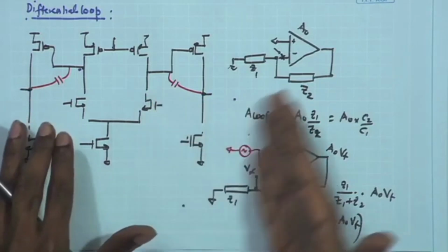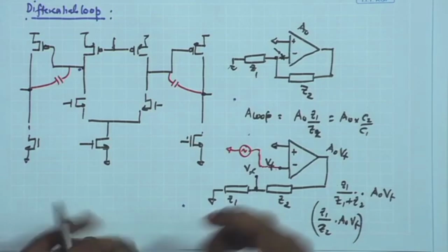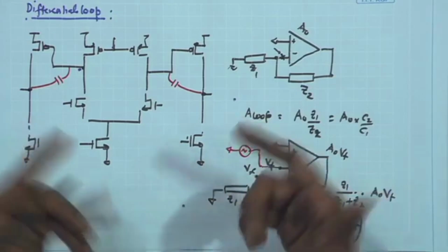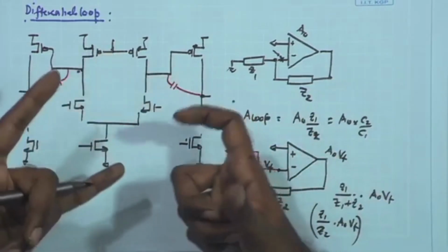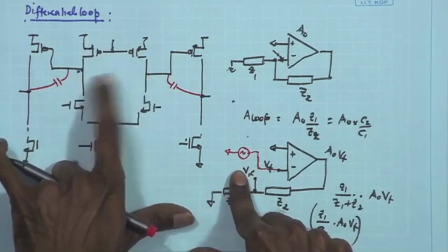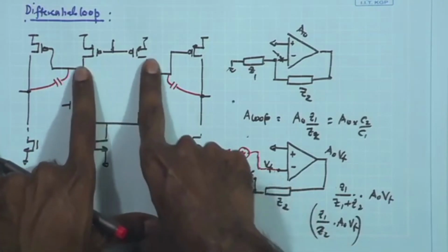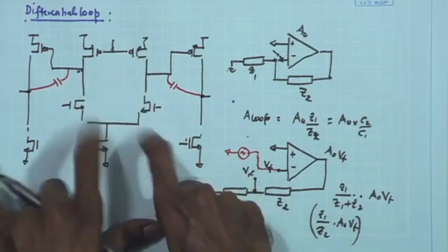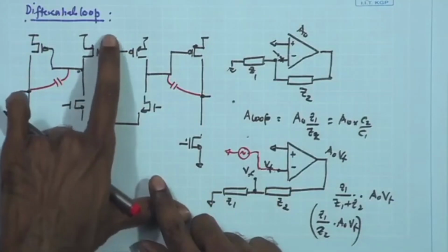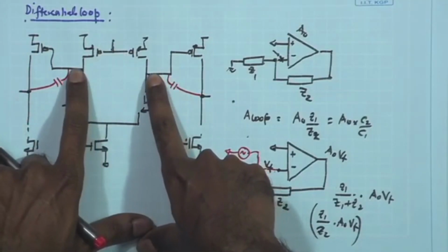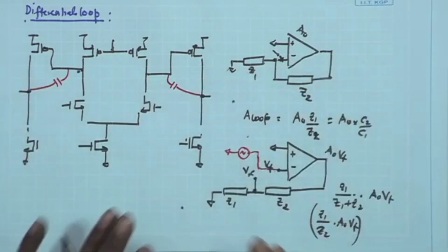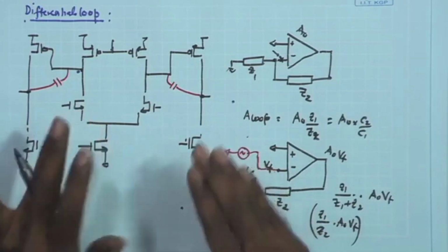As a result, for the common mode feedback case also, the magnitude of the loop gain was similar, not exactly the same, but similar. Now, why not exactly the same? You can recall that for calculating the common mode loop gain, you have to see the gain from this point to the output over here, the common mode output, and there rather than RO by 2 you get RO, because the impedance looking down into the drain of the MOSFET was pretty large. So, otherwise the order is similar. So, you have the gain from this point to this point given by GM RO, and finally, from this point to this point another GM RO by 2, and the common mode error amplifier is having close to unity gain provided the error amplifier is having a diode connected load.